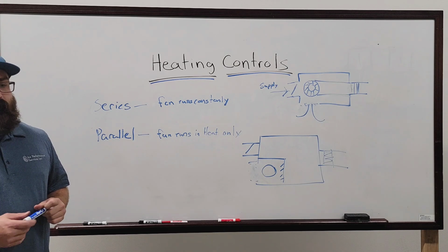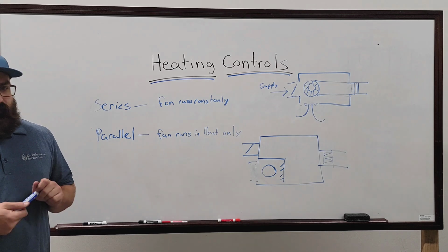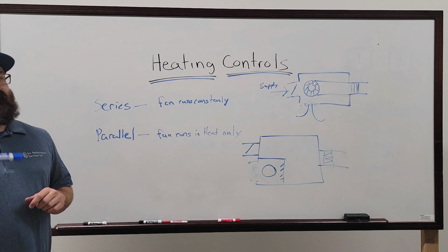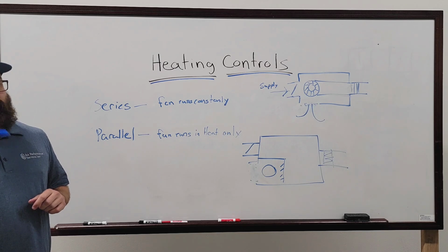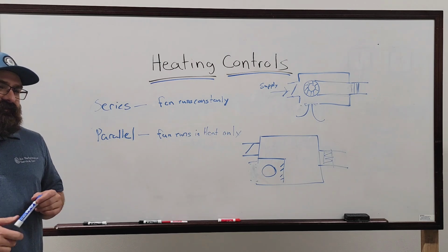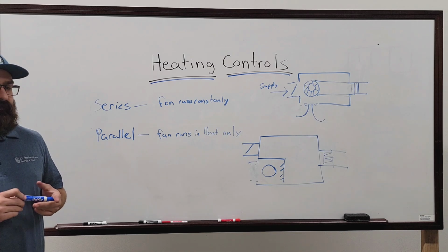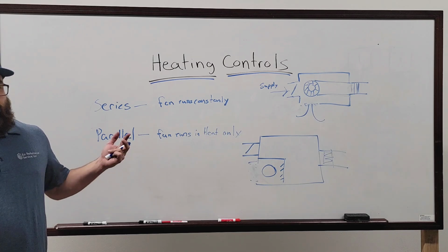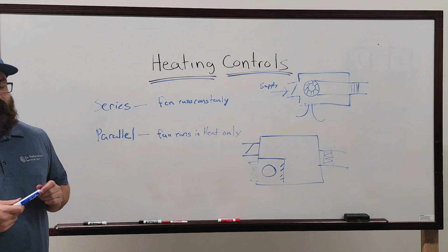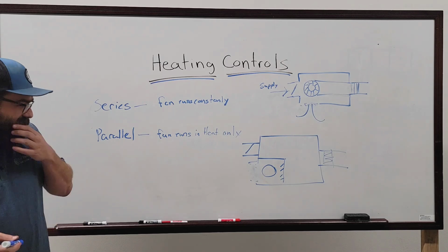So like if you have a VAV box, I know we did a couple downtown a couple months ago, like 3 or 4 of them did. The minimum the engineer specified was too low to bring on the heaters. So we had to up the minimums, which meant we had to go get an RFI and get it approved and all. It was a nightmare. But because somebody didn't do their homework and read the minimum airflow value on the box to make the heater work, you know, it is what it is.